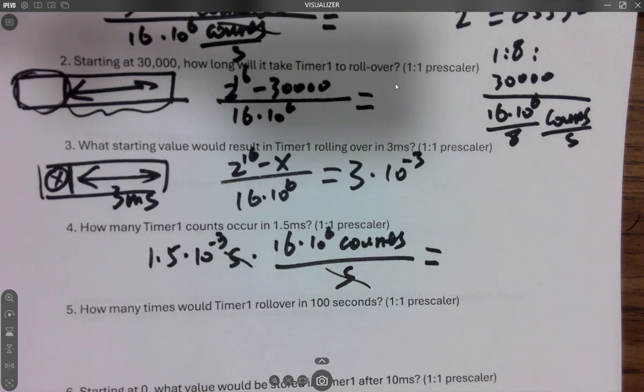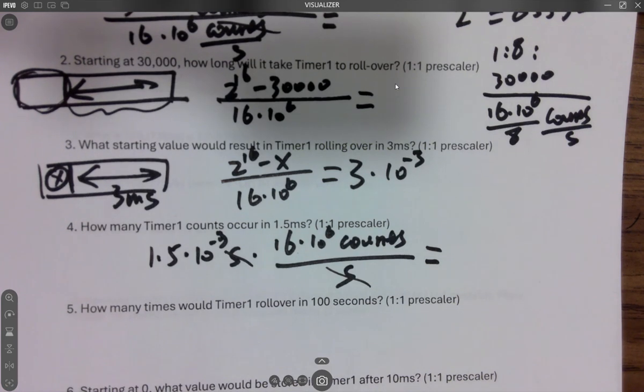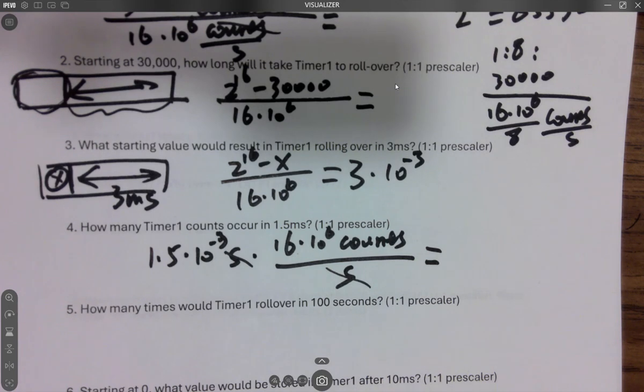That's reasonable, right? You're not expecting the temperature or anything else to change at 100 megahertz. You're not measuring that fast. It could be a few minutes. You measure a temperature, humidity, or anything else, your environmental data samples, and then send it. So you can put your microcontroller into sleep to save power, right? Every time after 100 seconds or a few minutes, you wake it up and transmit the signal.